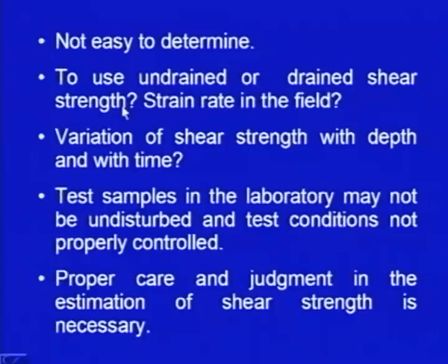Undrained and drained conditions depend on the strain rate, the rate of strain at which the failure occurs, and the permeability of the soil. If the permeability is very large, for example a sandy soil, you can treat it as drained and use the drained shear strength parameters. But if it is clay soil, or even silty soil, then what is the rate of strain compared to the rate of dissipation of pore water pressure? That is very important. So, drained and undrained conditions are complex phenomena, and we have to give a reasonable solution. We have to think in terms of these things.